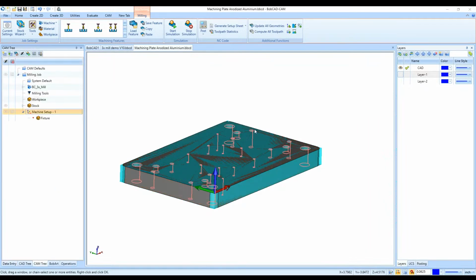And now it will pick up all of the different hole sizes. I can highlight each one and it'll highlight with a different color what the .291 diameter holes are. Highlight this one, it'll show us 1 inch, .102 diameter, .629 or .630 it looks like, .315, .366.